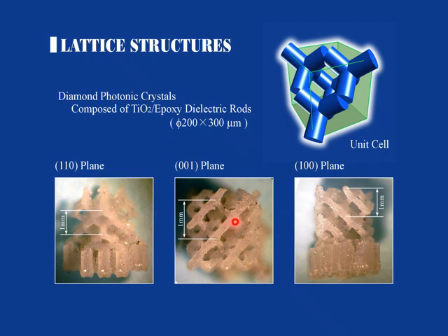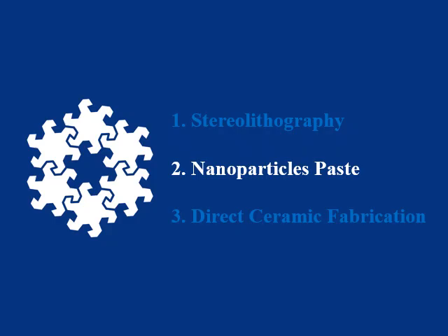However, in this case, we used only a 0.1 millimeter, 100 micrometer spot size laser beam, so it is difficult to create micrometer order structures like this. And the most important thing, these are composite materials. The epoxy matrix absorbs the terahertz wave, so we have to create clearer micrometer order diamond type 3-dimensional structures using a perfect 100% ceramics lattice.